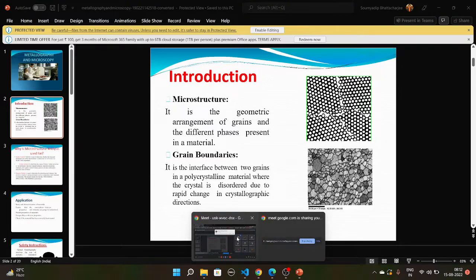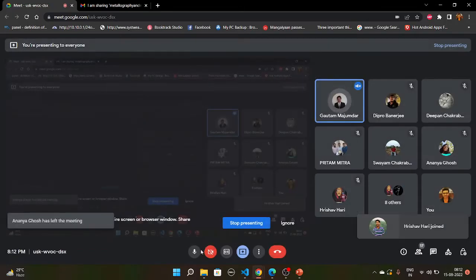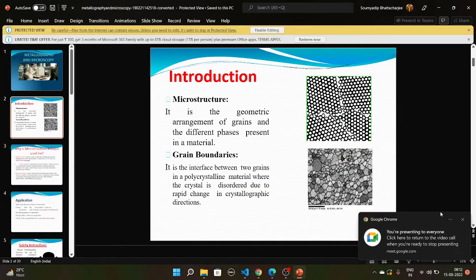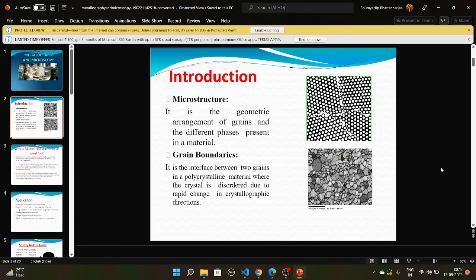Now, the question is, suppose you have made the specimen very hard. As you could guess, if you make it very hard, because of the forces coming at the tip of the cutting tool, it can crack immediately. So you have to sacrifice some hardness and induce some toughness into it by adopting another heat treatment over the heat treated one. That is what is called the tempering process. So this terminology will come across.